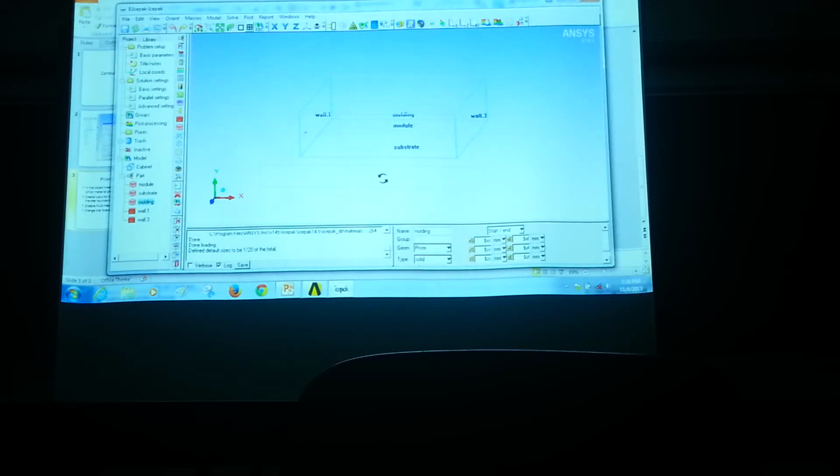We're modeling pure conduction right now. When you say pure conduction, from a physics point of view it's not really pure conduction. What you're saying is, I'm decoupling the convective heat transfer from the conduction heat transfer by putting in a heat transfer coefficient. For the impact of the air, I did all kinds of experimental work and found out that I can put an H at a distance.